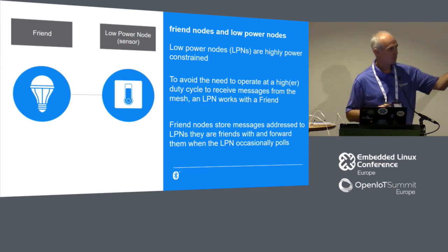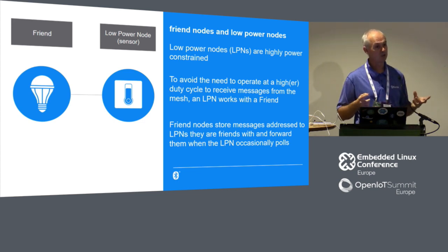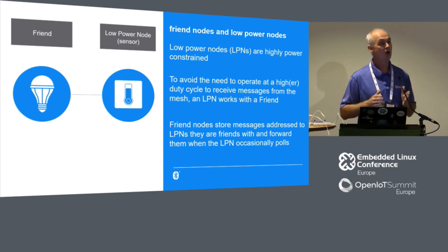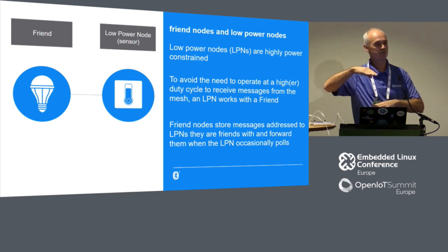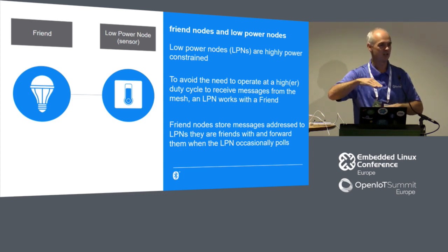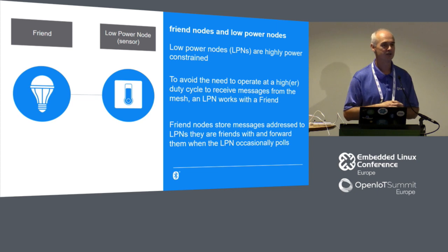So imagine, per the slide here, I've got a temperature sensor, and its job is to report the current environmental temperature only if it exceeds a certain upper level or falls below a certain threshold. So most of the time this device is quiet. Using the radio is what we're concerned about as engineers. That's what consumes power. But this device probably transmits 4 bytes every year, when it's a hot day or very cold in the winter. So that's all it does. So at this stage in the description of my device, I don't have a power problem. It's fine. This is a very efficient device.